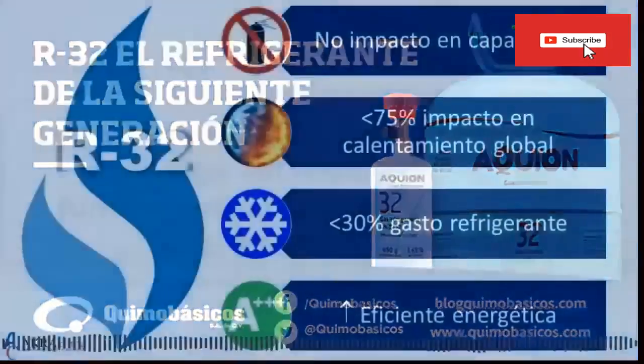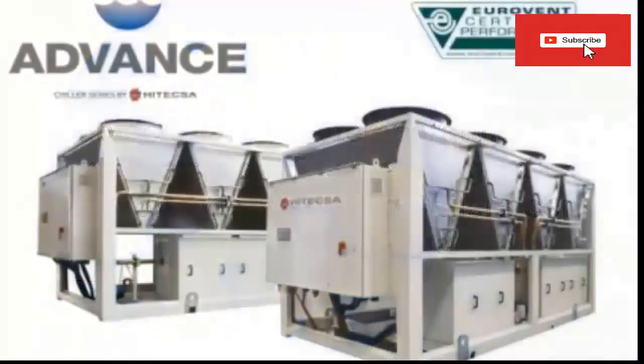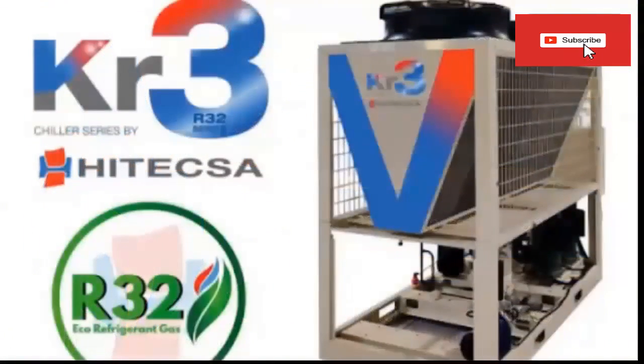Due to the high discharge temperatures of R32, the operating range of R32 chillers is more limited. 10. For operation in ambient temperature conditions greater than 45 degrees Celsius, R452B or R454B are better options than R32. 11. Manufacturers have selected R32 for their scroll compressor chillers because of its lower impact on the environment.